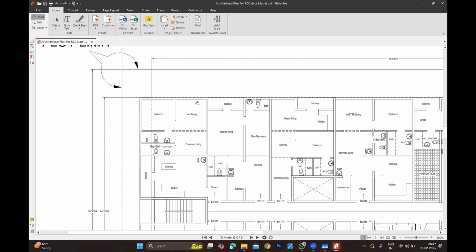In that case, try to keep the core wall closer to the CG of the building. You cannot keep it exactly at the CG, but at least with a bit less eccentricity. If you knowingly keep the core wall far more eccentric, then unnecessarily you will get huge movement. The tension will also be very high. So what is going to happen? It is going to demand more wall thickness, column size, beam or foundation, everything. Understand what I'm saying.